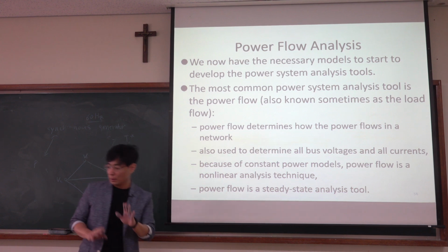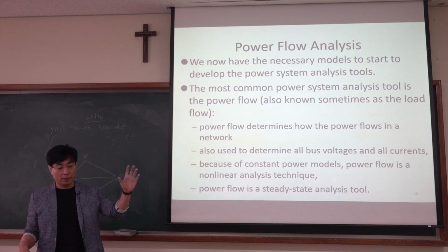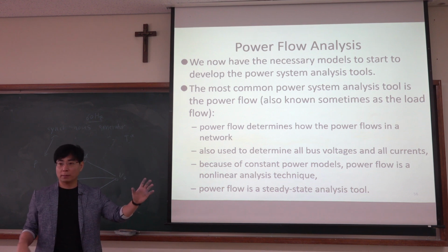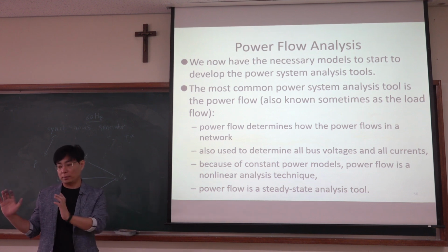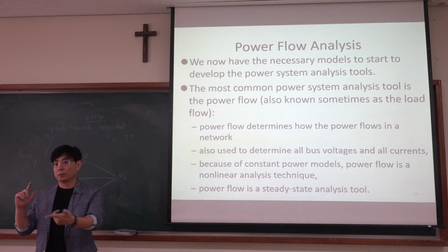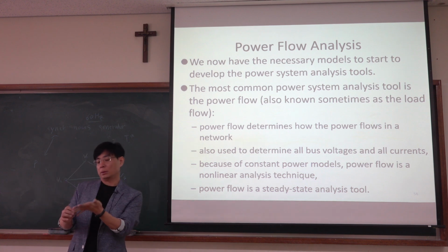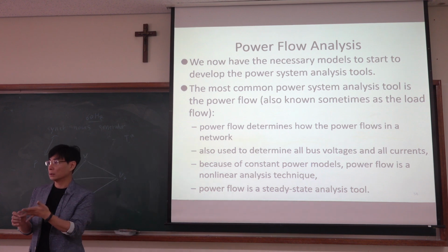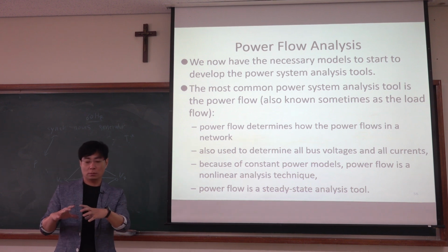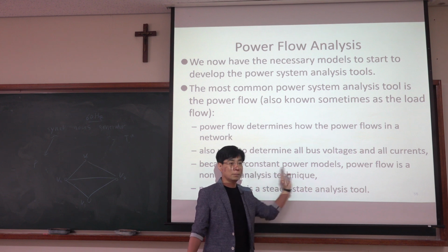Actually, there are different types of load, like AC synchronous three-phase motors. But another type of load is based on power electronic devices: laptop, computer, TV, most of the home appliances, right? So now you see why we need this kind of concept, the constant power model.